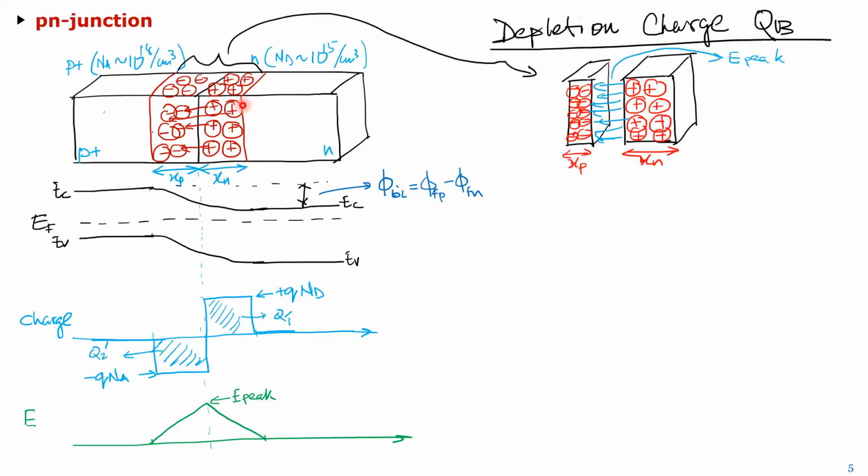So what you do is, if you take these two blocks here, I've just taken out these two depletion areas. And if I want to find the charge in this or this, which is the same, right, they're just opposite magnitude, then I can apply what's called Gauss's law, which is actually one of Maxwell's equations too. It's a fancy term, but essentially it just tells you that if I enclose this entire volume, and if I calculate all the electric field lines coming out, it should be equal to the total charge divided by the permittivity of the material inside.